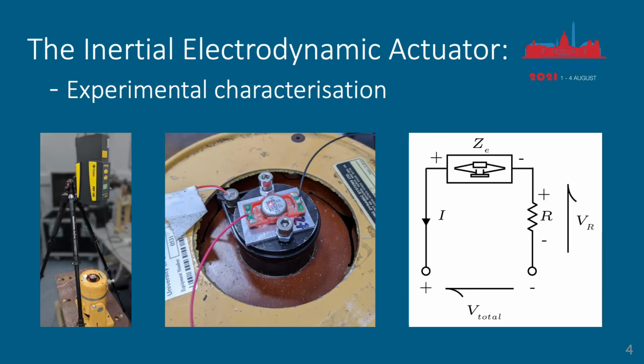As I already said, we were planning to characterise the actuator parameters ourselves for accuracy, and we did this with two experiments. We measured the dynamic response to base excitation, and we also measured the dynamic and electrical response to an electrical input. From these two sets of measurements, the full set of parameters can be calculated.